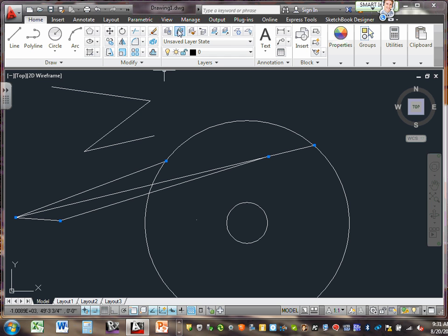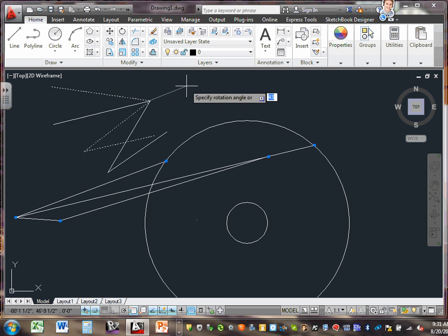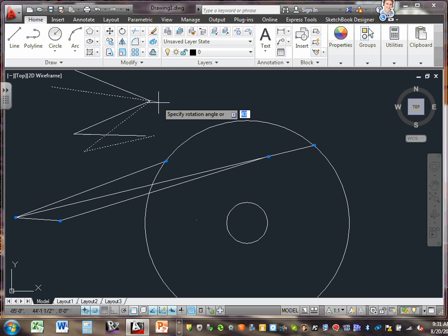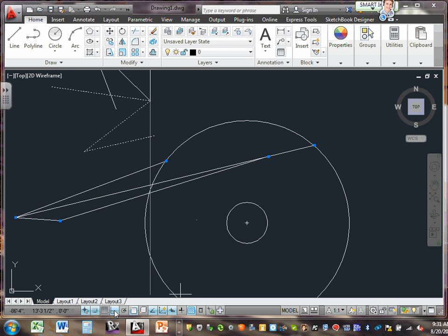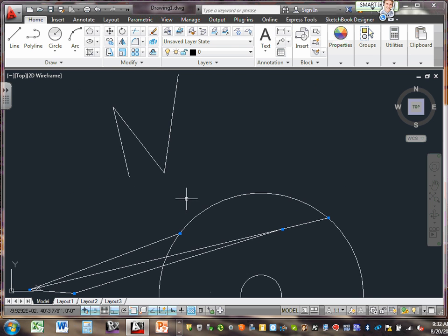I grabbed something. I'm going to rotate it. Highlight the thing that you want to rotate. Right click. Specify the point. Can you guys see now I'm rotating? Everybody can see I'm holding and rotating. Where do you want to rotate it? This way. If you want to put your ortho on, now you start moving in ortho. Rotating it in ortho. There you go.